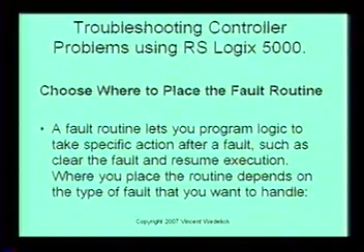Choose where to place the fault routine. A fault routine lets you program logic to take specific action after a fault, such as clear the fault and resume execution. Where you place a routine depends on the type of fault you want to handle.